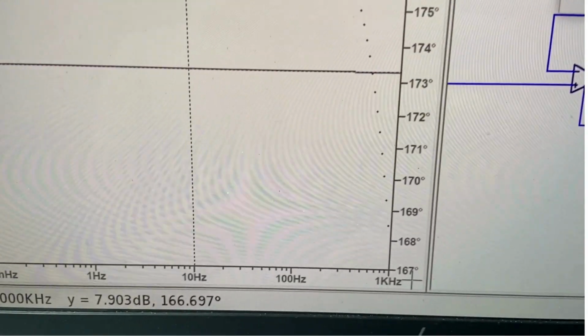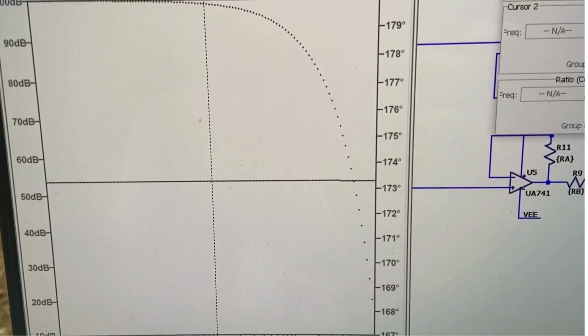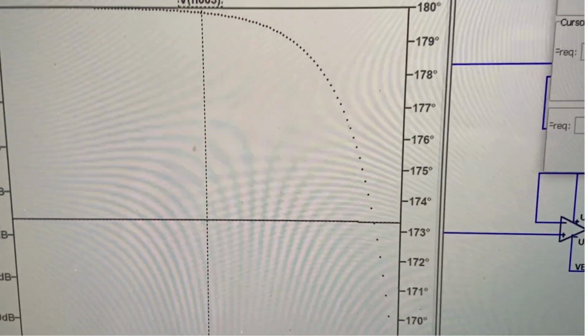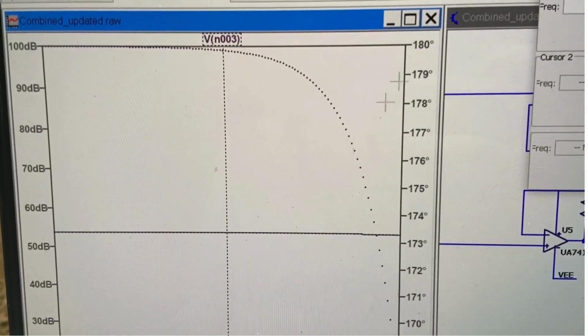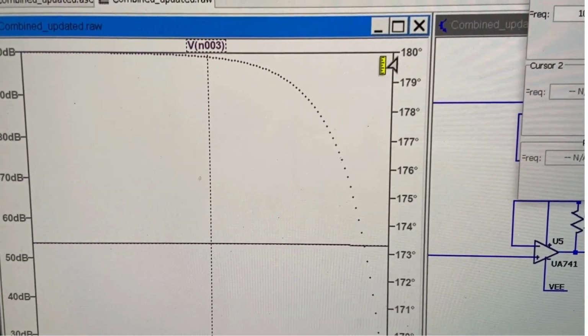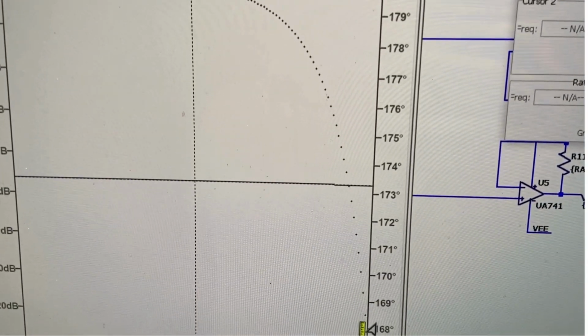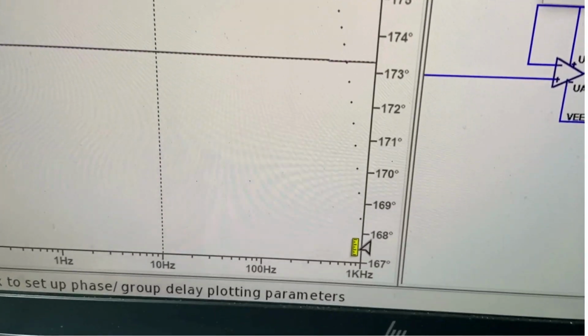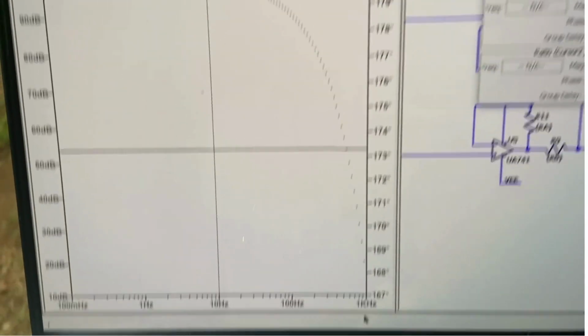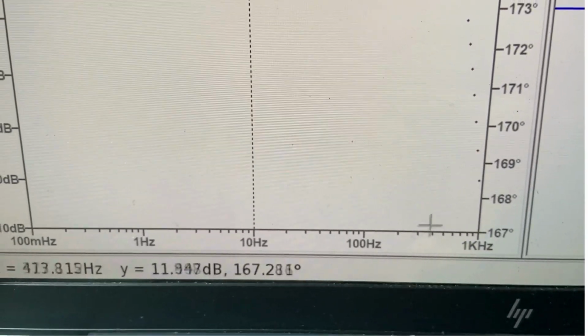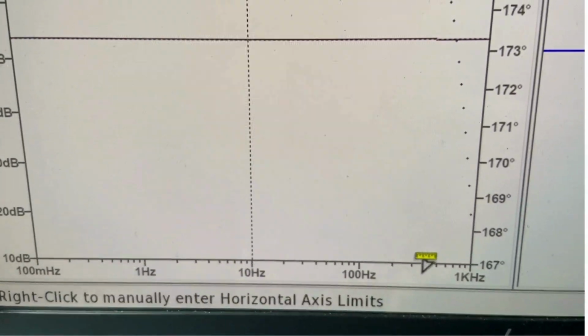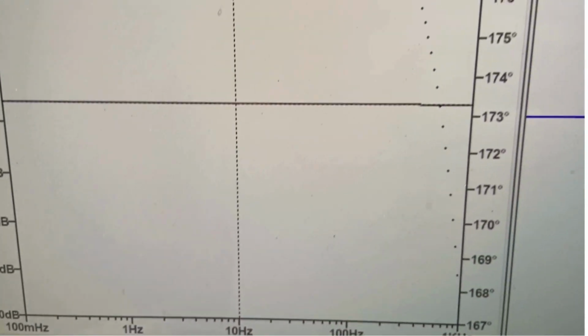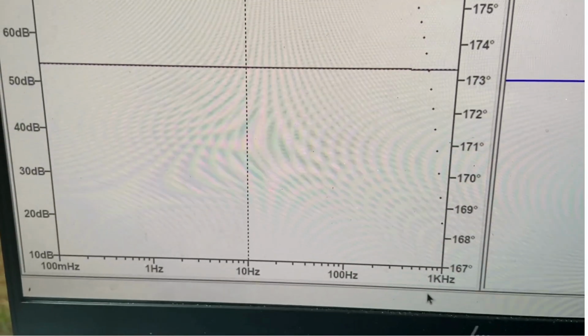The instrumentation amplifier essentially makes sure that there's a phase difference of 180 degrees, and we are seeing that the difference is not very large, from 180 degrees to 167 degrees. Moreover, it's not a point of contention in our case because this happens only at very large frequencies of around 1 kilohertz, and we are operating at very small frequencies, closer to a much lower value.